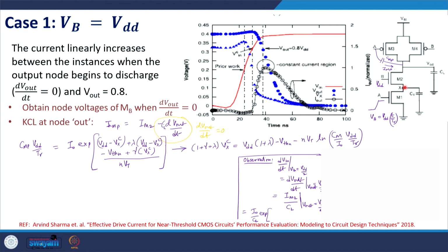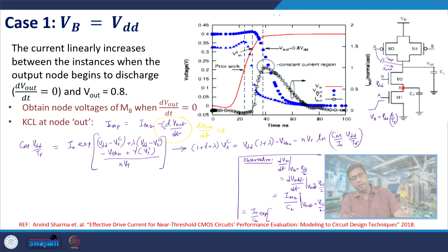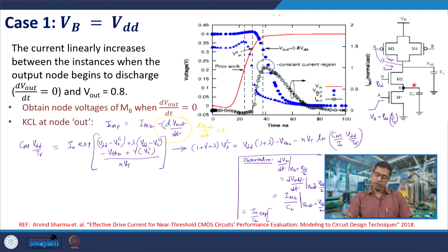Therefore, Vx would also be almost a constant value, very slowly changing, and it should stay almost constant with change in FO also. So for the 50% VDD value, this Vx should be constant with change of FO. That is because the current through M2 is almost constant and very slowly changing, and the input voltage, and therefore VGS of M2, would be almost constant.